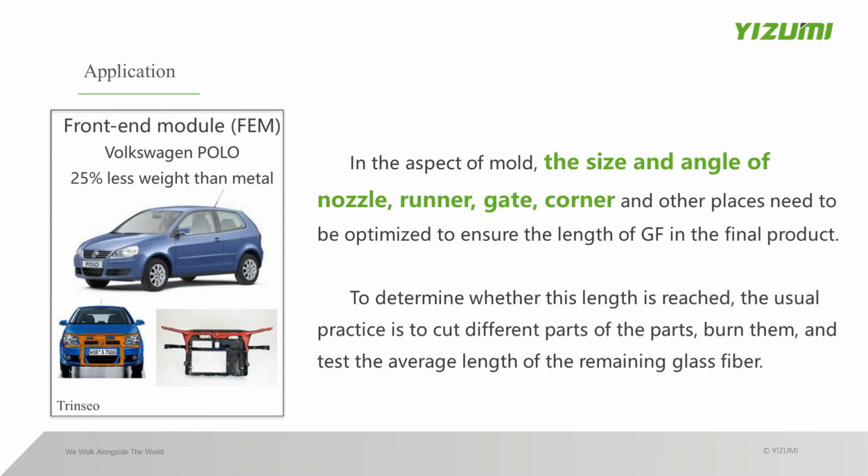According to our experience, to determine whether the length is reached, we usually cut different parts from different positions, burn them, and then test the average length of the remaining glass fibers. That's what we do in the third part.